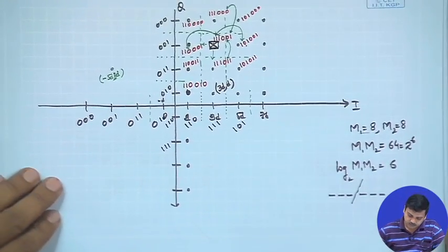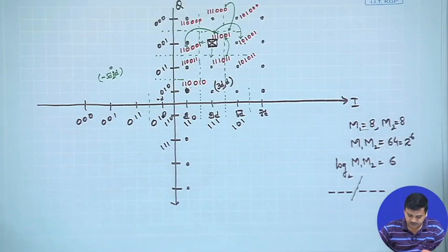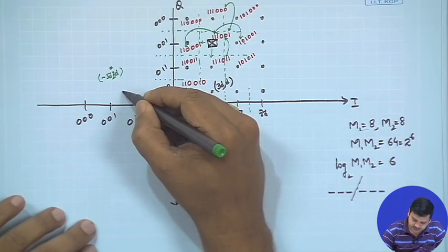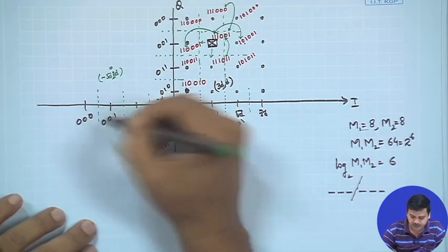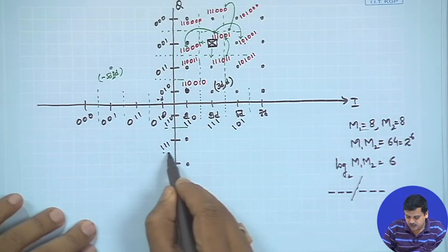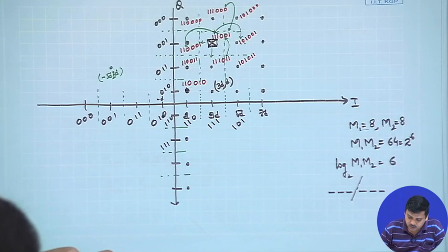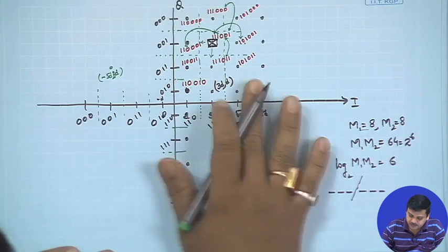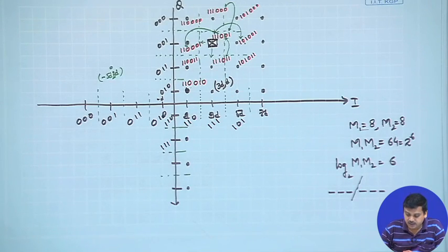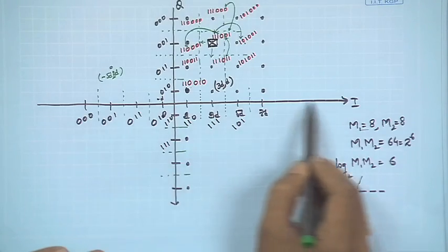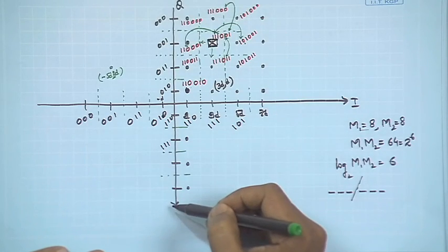So, you have your decision boundaries which are clearly symmetrical, and this of course appears for the case of memoryless modulation, right, and by symbol detection. So, if you are doing this and in this pattern, as I have already mentioned, you can use a single PAM lookup table for generation and you could use a symbol decision threshold for detection as well, because you can clearly see whatever we have in the I axis, you could use a similar thing on the Q axis.